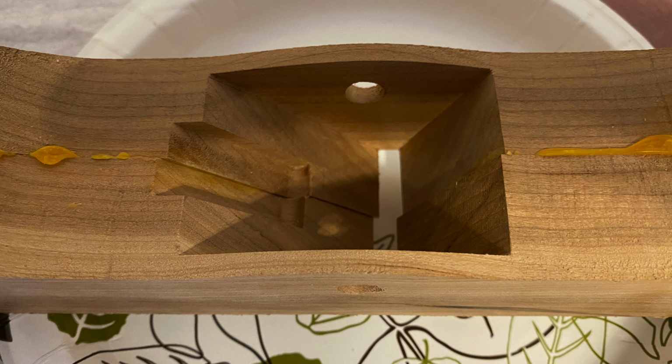So after putting the CNC back together, I wiped down the X, Y, and Z guides and threaded rods with mineral spirits and then sprayed them with a dry lube. Once I had sprayed everything, I wanted to exercise all the axes to distribute the lube evenly.